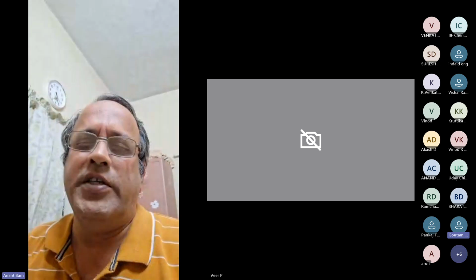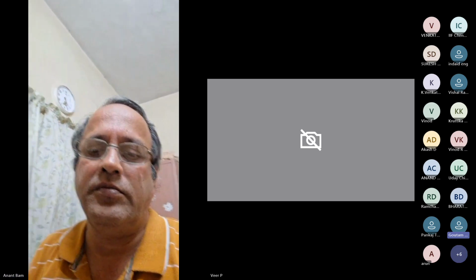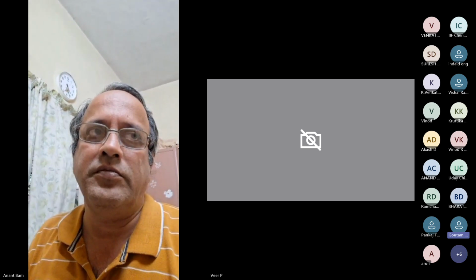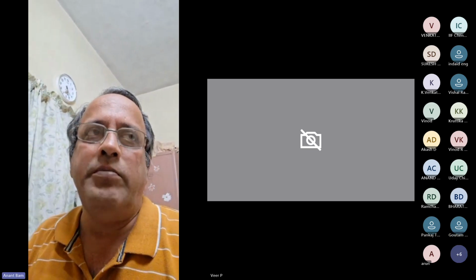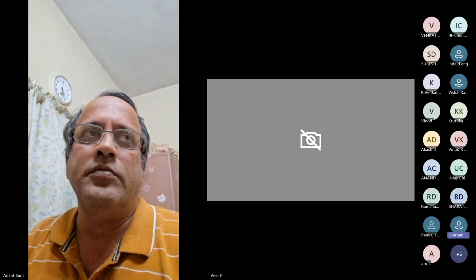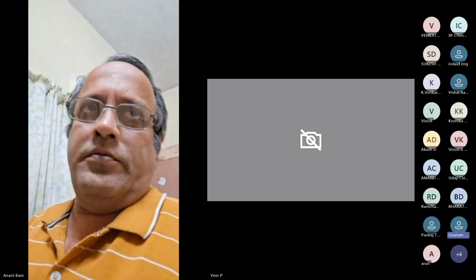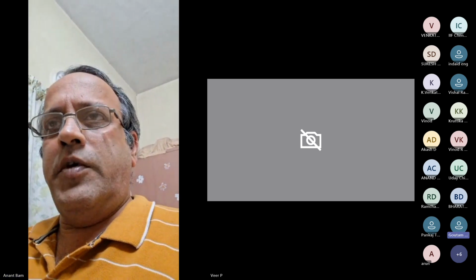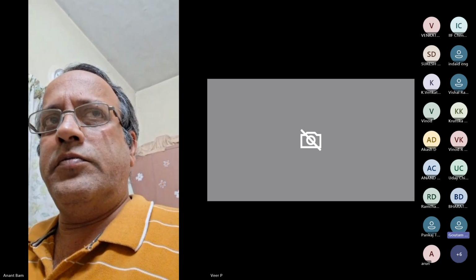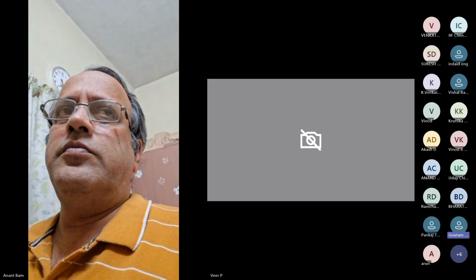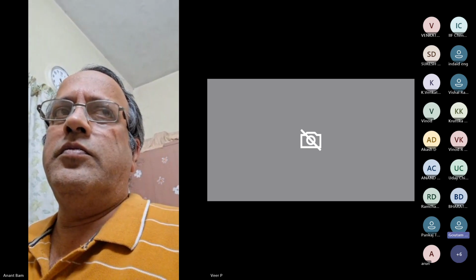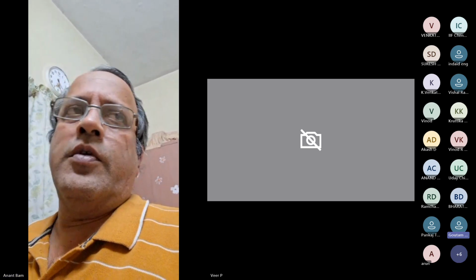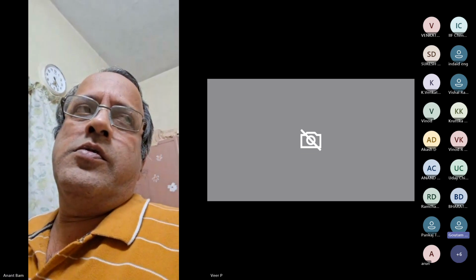The typical alloy composition is silicon around 8.5 to 10, Fe 0.15 max, copper 0.03 max, Mn 0.55 to 0.8, Mg 0.15 to 0.35, the rest trace elements at 0.1, 0.15, and titanium 0.1 to 0.2.